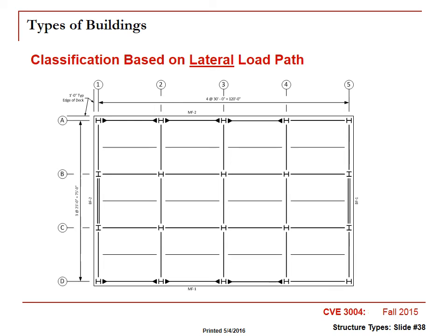So that's a frame that has maybe an X bracing or a diagonal bracing, or maybe what we call chevron bracing. But that's what that stands for. So again, what this is trying to show you is that we can have certain systems that resist lateral loads.